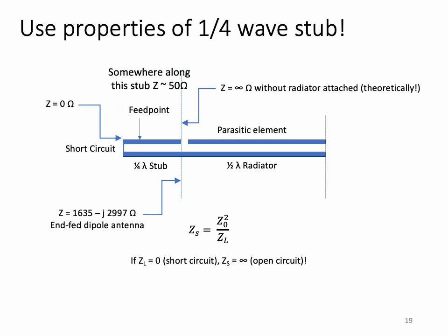In our case, we're making a flexible J-pole out of twin lead. A notch is cut in one side of the twin lead to create a quarter wave stub at the lower end. To the right of the notch in this diagram lies the half-wave radiator. Note that there's an effective parasitic element that is created by the notch. That's this element here. The element is not physically connected to the rest of the antenna, but rather acts as a parasitic element which tends to broaden the frequency response of the dipole. Remember that fat antennas typically have wider bandwidth properties.